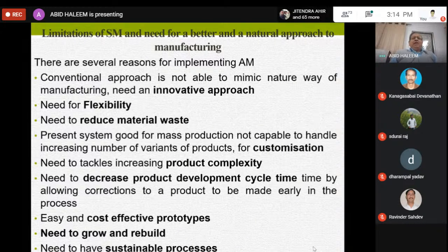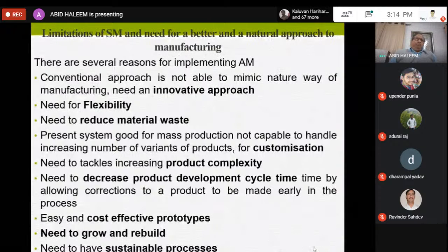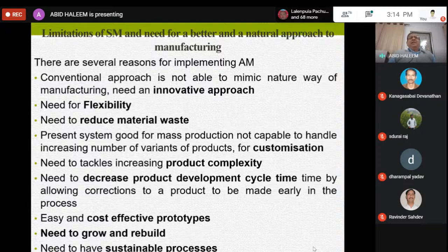From the blank, you cut it. You cut the blank through a cutter or a hob to get the respective shape, the shape that we desire. The number of teeth, the addendum, and everything that you want, you get from that. To understand this, to make a gear, we have been subtracting the material.